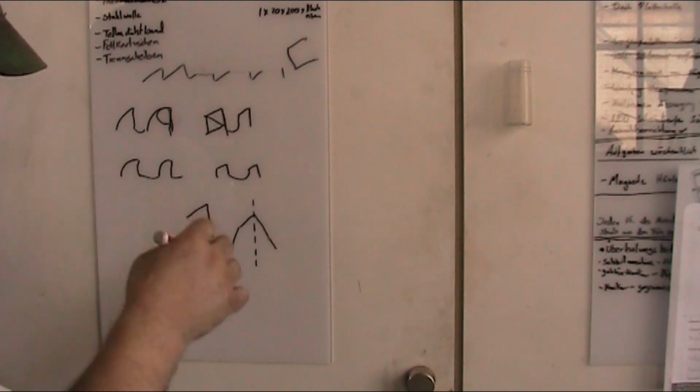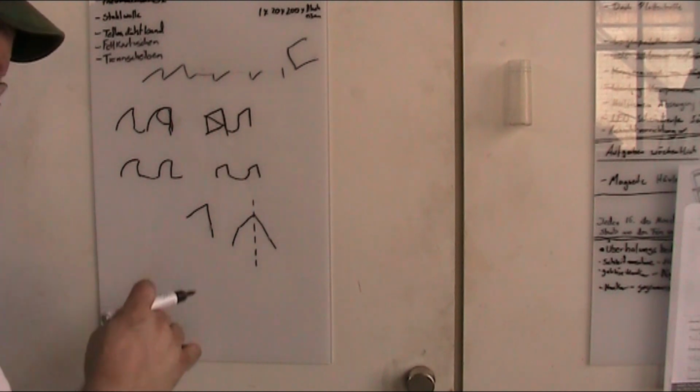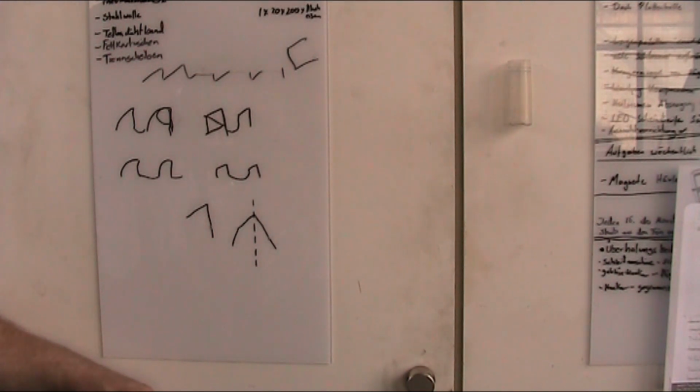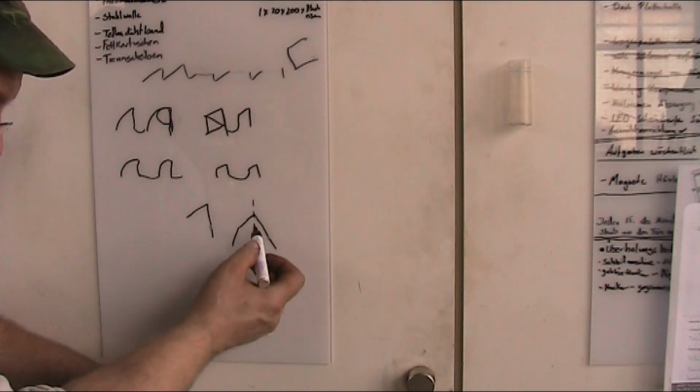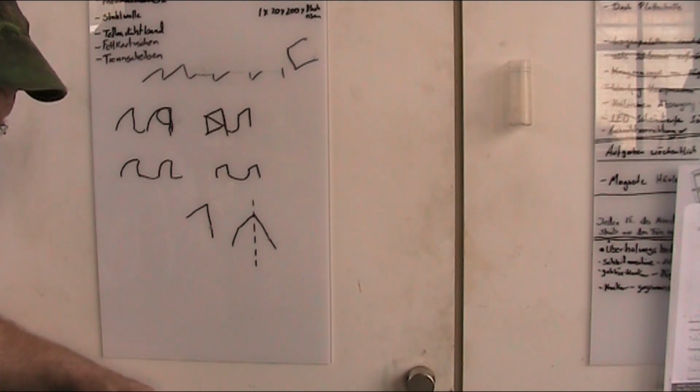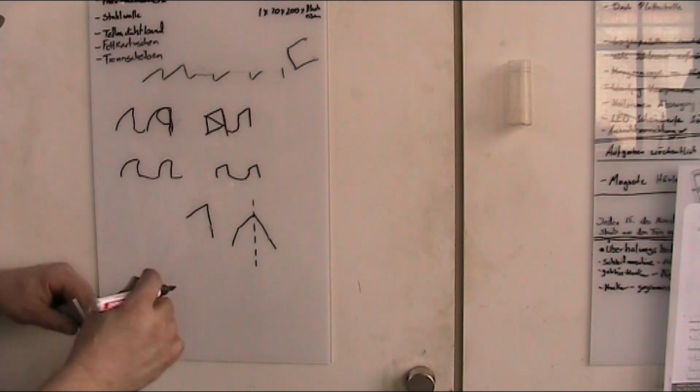These are for extremely hard materials like coated melamine, or melamine-coated MDF, plywood, stuff like that, because the melamine is, although it's a plastic, extremely hard, and yes, it is actually as hard as steel. And as this tooth passes through, it needs a negative rake angle on the front of the tooth in order to maintain its edge.